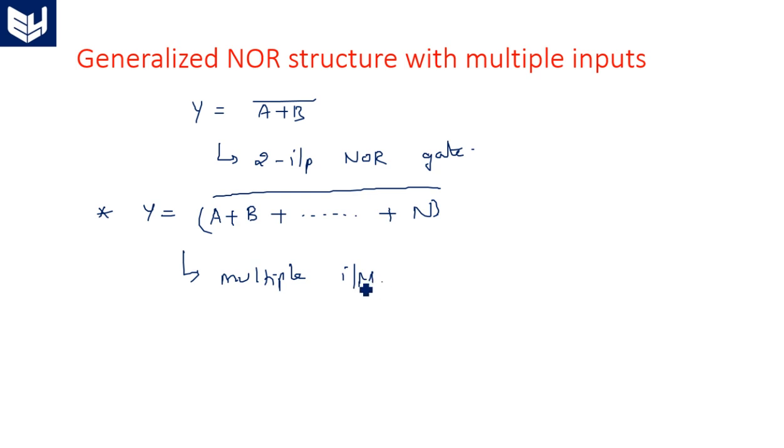See how many number of inputs we have, that doesn't matter, but the thing is we have to use a depletion mode transistor always between output and VDD, and for the realization of the NMOS transistors, a parallel set must be connected always in the pull down network for NOR realization. NMOS transistors, that may be 1, 2 or 3 and so on, 2 or more for NOR realization.